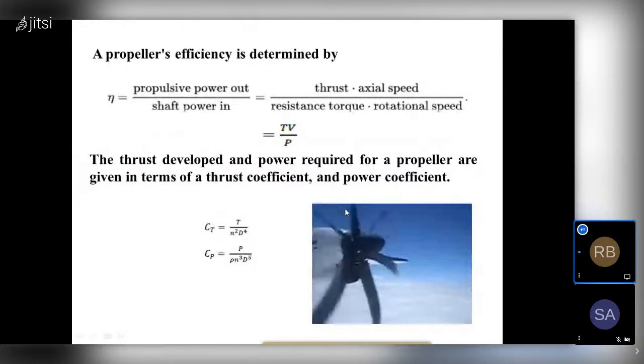So here, if I talk about the centrifugal force, we can say that it is caused by rotation of a propeller and tends to throw the blades out from the center line. Okay. And torsional or twisting force, that is on the blade itself, right? That is caused by the resultant of air forces, which tends to twist the blade towards a lower blade angle.